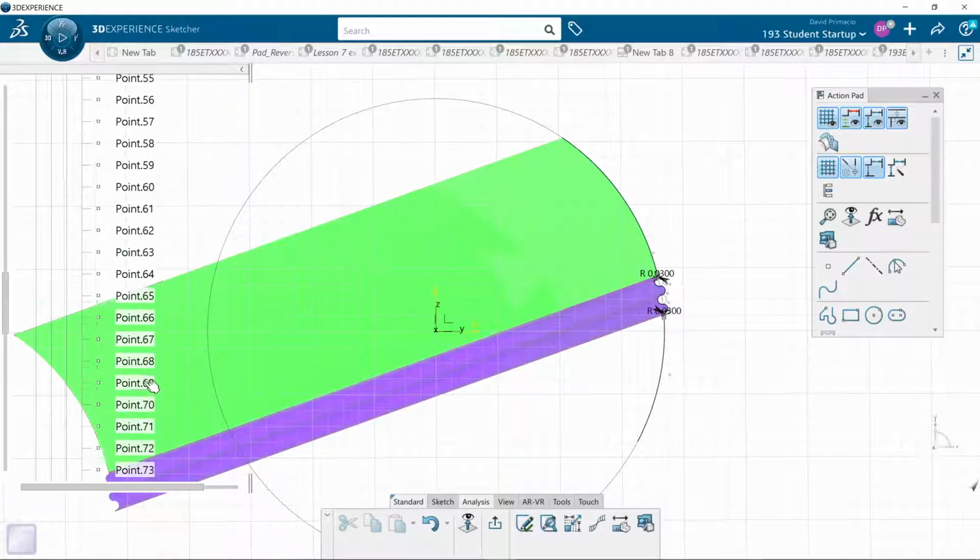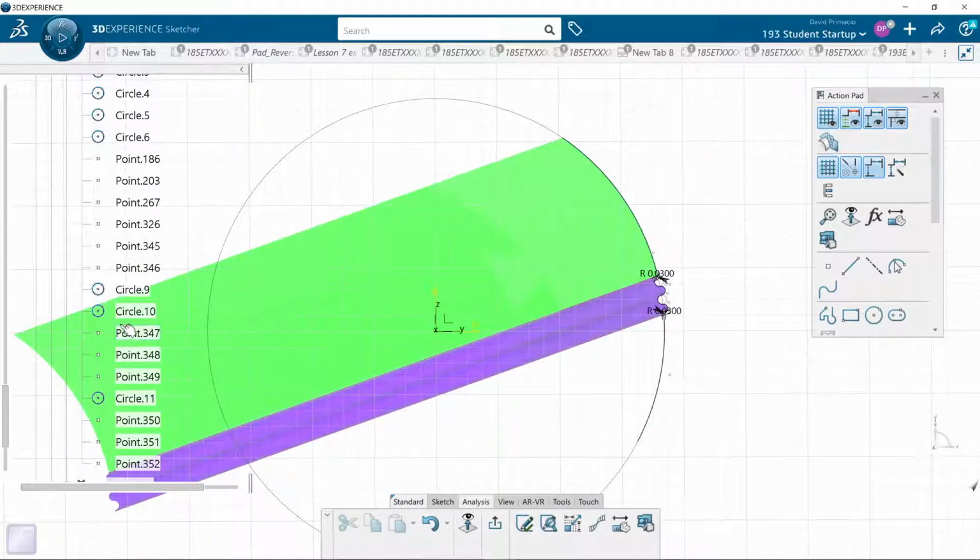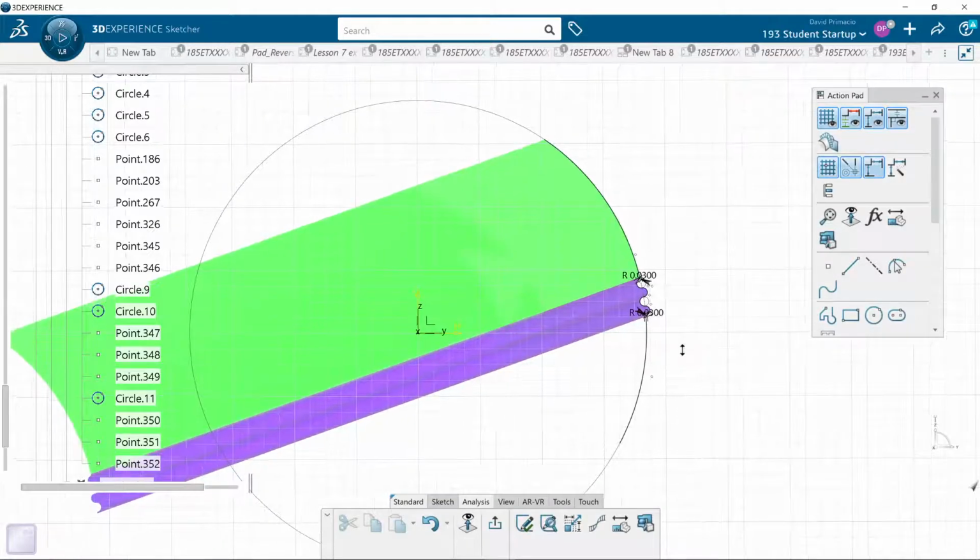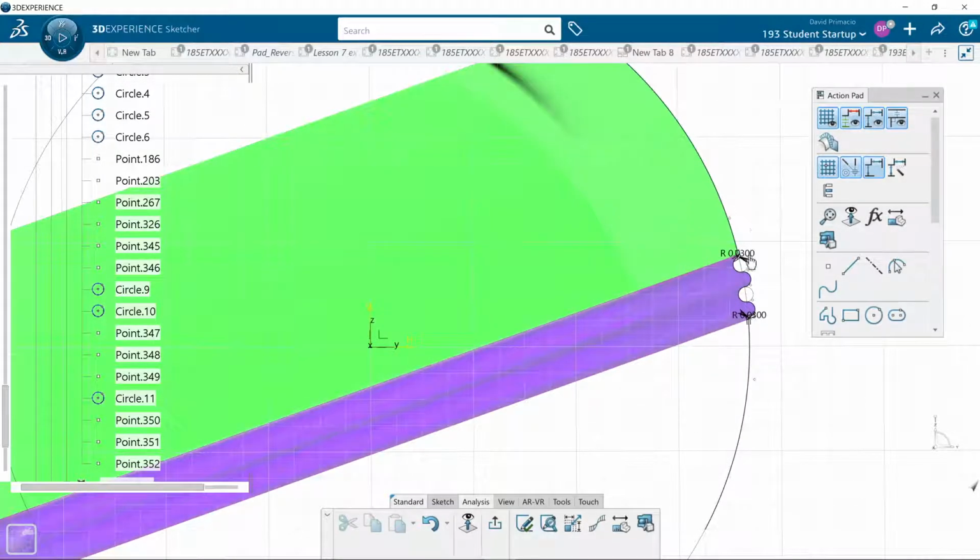So all those points that I had created, it'd literally be hundreds of them. To create the spine, you'd have to create all the points. Well, I guarantee you some of them weren't perfectly along the curve. One would be above and one would be below, and we would get positive, negative values. That's why we get ripples in our surface, because that's how it was designed.